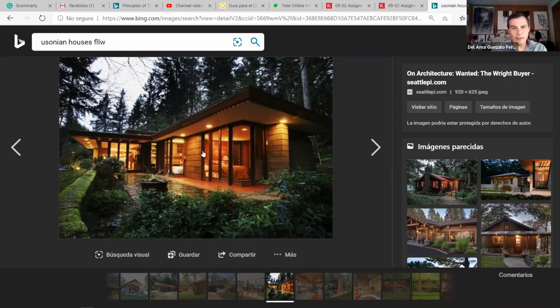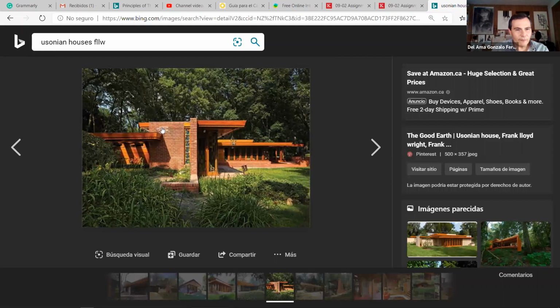So we have to design large windows, south-oriented. We have to design the right size or the right length for the overhang. And in northern facades, we have something with very small openings and something that is not as open as the south facade.